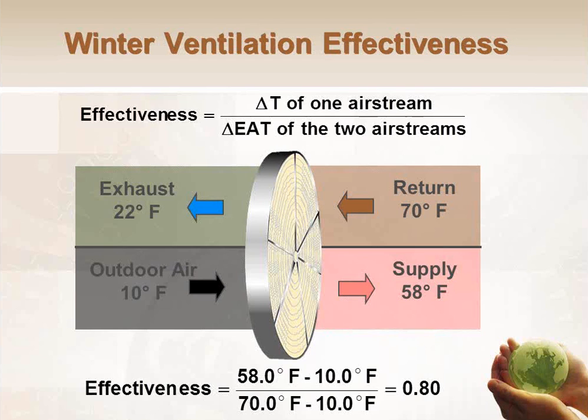Syed asks if this is applicable to isolation rooms in hospitals as well as labs. The answer is going to depend upon the specific code that you're looking at and the type of heat exchanger you choose. In an isolation room, you probably have to have absolutely 0% leakage, and I'm going to talk about leakage in a minute here. So you're going to have to choose an ERV technology that will give you guaranteed zero leakage, and you're going to have to rely on that particular governing body, here where I'm at, the Illinois Department of Health, to allow you to use ERVs. So you're probably going to be able to do it with a fixed plate, but probably not with a wheel.